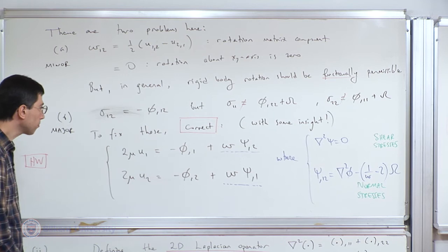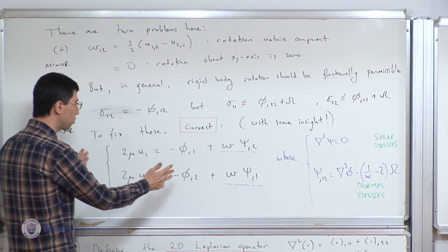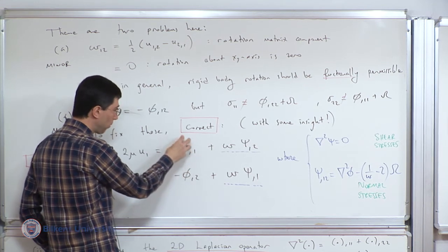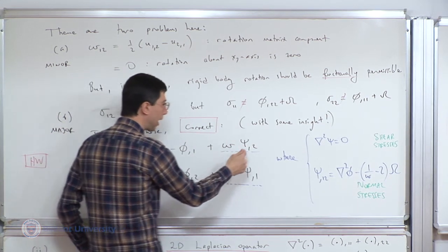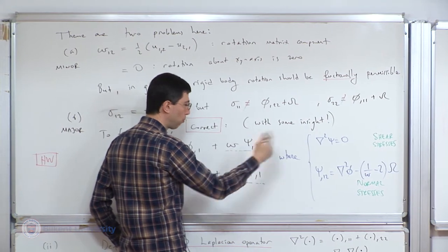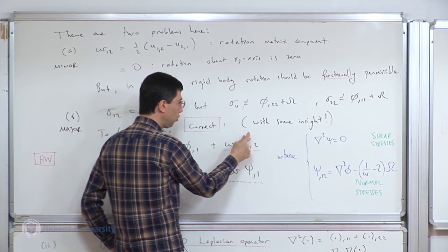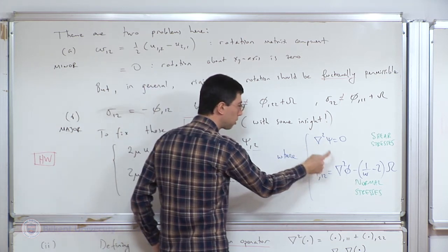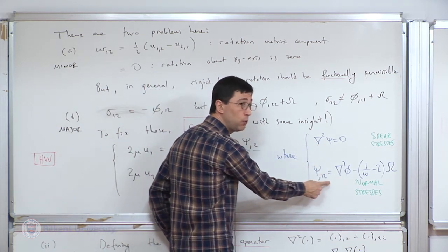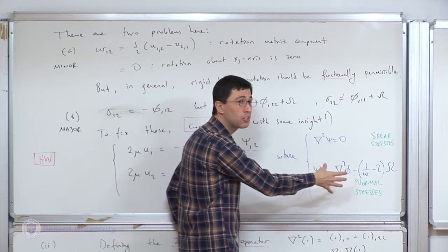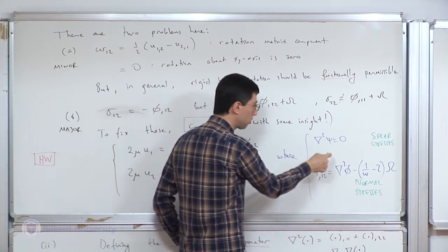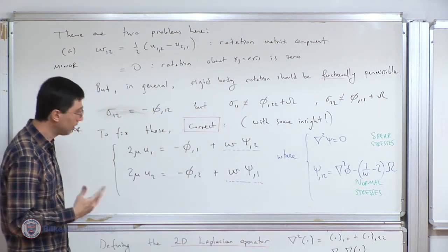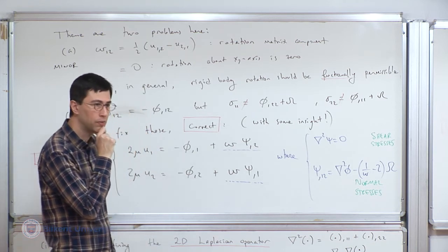All right? So if you want to construct the stresses, if you have already found out what the Airy stress function is, it turns out, therefore, it's not sufficient for a consistent result with our proposal for the form of the stresses. You need to also find the function psi. Luckily, we have some constraints for that function, which actually is not making the process cumbersome, just the contrary. These constraints will allow us to eventually find what that function is. Again, I will have an example and you will see how all of this works.